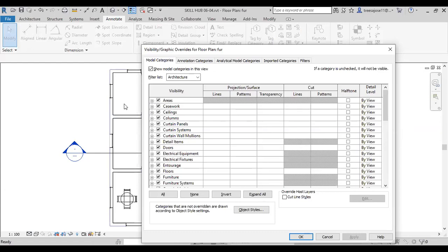For avoiding that, you can create a template. That time you can select the template, and automatically that will be updated. No need to make the changes on the independent floors. For example, in the case of 10-story, 15-story buildings, it will be difficult. For all the 10, 15 floors, we need to change the parameters. That is difficult. In that case, we create a template. Okay. I will show you how to create it.